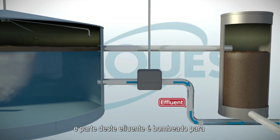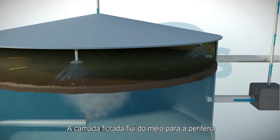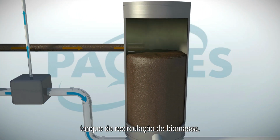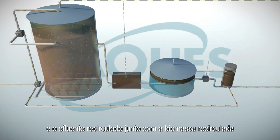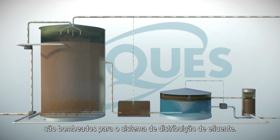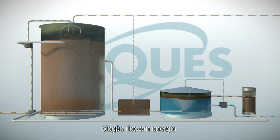Part of this effluent is pumped towards the top of the flotation unit and is sprayed on the outer sides of the flotation layer. The flotation layer flows from the middle of the unit towards the side and flows towards the biomass recycling tank. The biomass is recycled from this tank to the bioreactor. Together with the incoming wastewater and the mixing flow, the recycled biomass is pumped into the influent distribution system. In this way, the biomass is retained in the system and will contribute over and over to the conversion of the organic compounds into the energy-rich biogas.